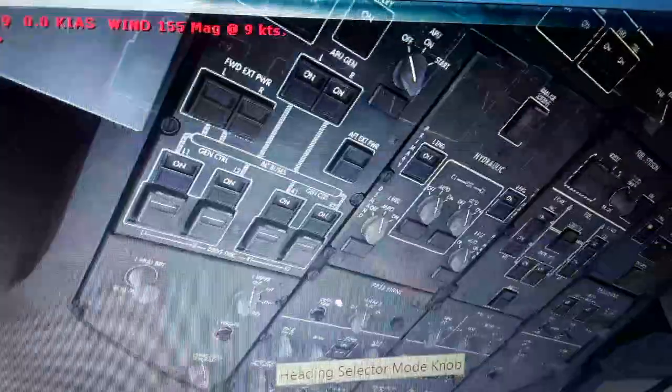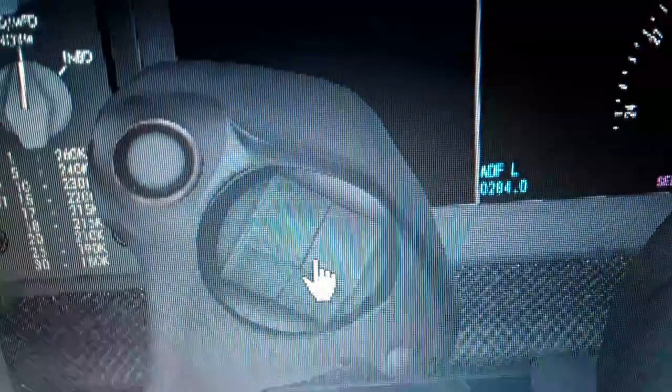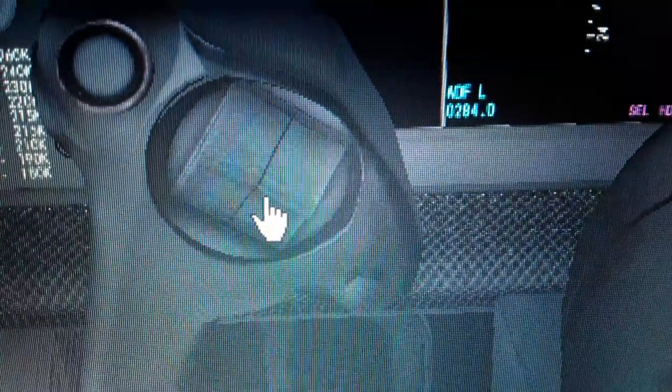The flight control computers actually commanded the motion of the autopilot, and now the flight management computer. So you have only the manual trim switch, because we have the normal, the alternate, and the direct mode. So this is the normal, which is also manual for this function for the horizontal tail trim.